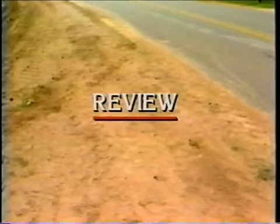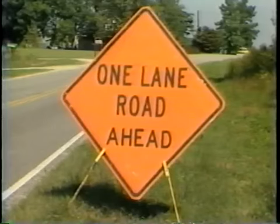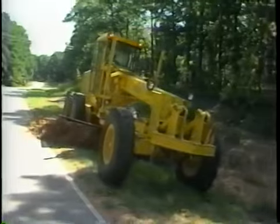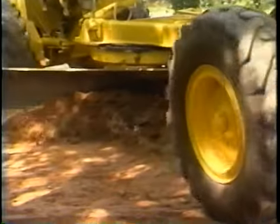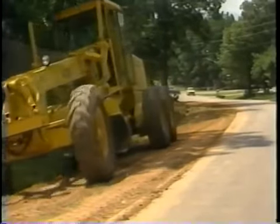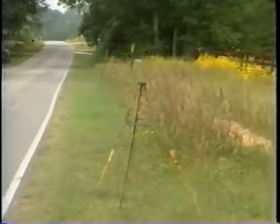Now, let us review the steps required for reshaping of shoulders. Number 1, place proper traffic control. Number 2, blade shoulder with motor grader and windrow material at the edge of pavement. Number 3, spread material back across shoulder at the proper slope. Number 4, compact shoulder with the motor grader. Number 5, remove traffic control.